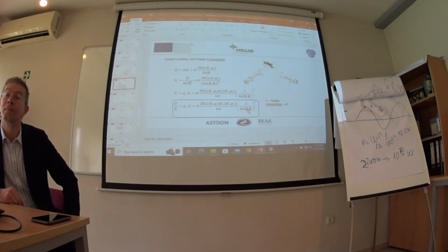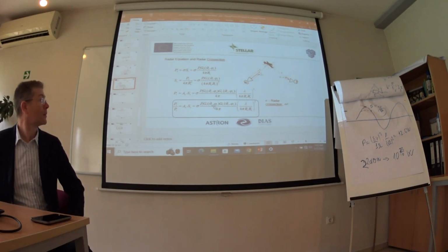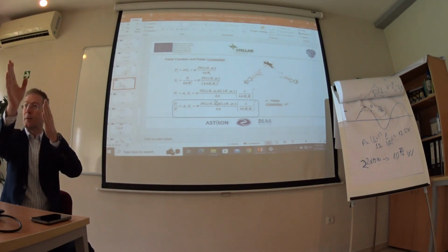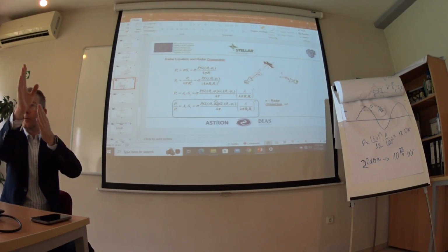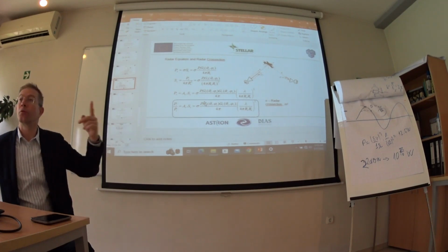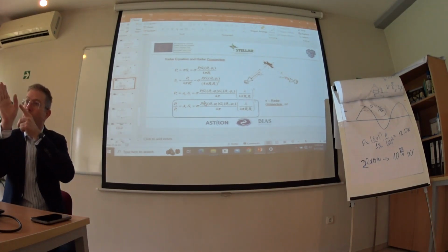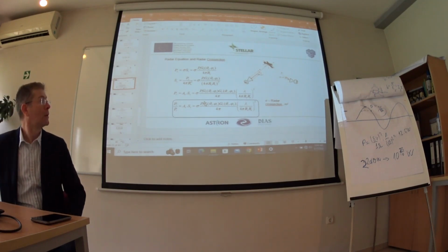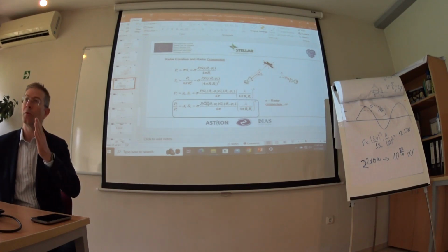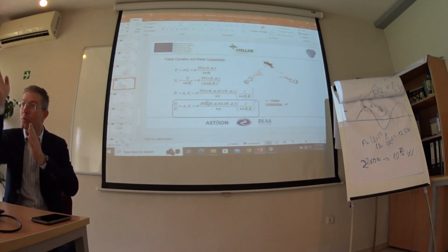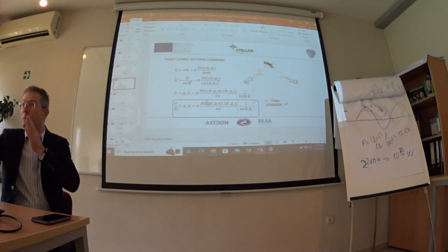Those angles that are written there, where do we measure them? These angles are angles of direction of the radar. Because sometimes the target is not toward the peak of the antenna, it's on a side. This angle tells us that we have to use the power pattern of the antenna in order to calculate how much power we transmit toward the target. It's just important to keep in mind not to use the peak gain of the antenna, but the gain that is applicable to the specific direction.